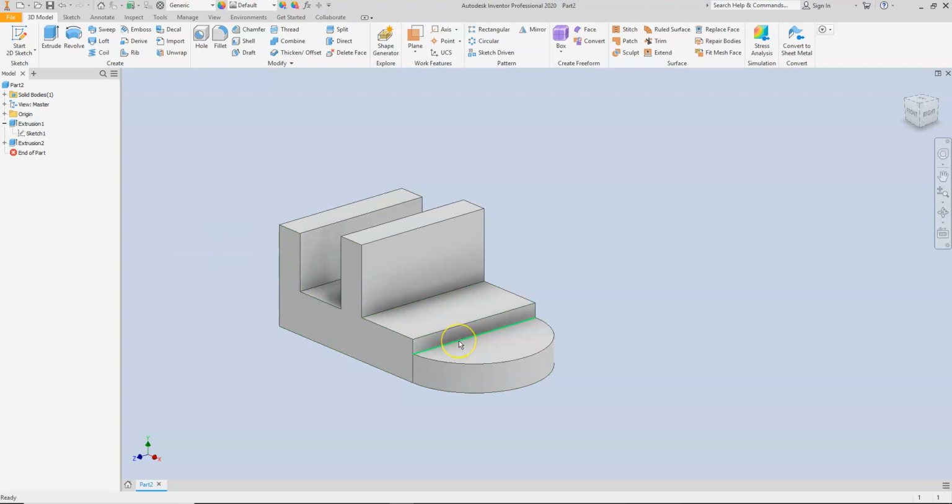For a part this small, it doesn't make a big deal, but when you start designing multiple complex parts, and you have one dimension change, and you continue to build these parent-child relationships with sketches where one surface is going to be dependent on something else, if something else changes, you want to make sure that those surfaces or those relationships still exist. So it's a good habit to get into looking at these relationships.